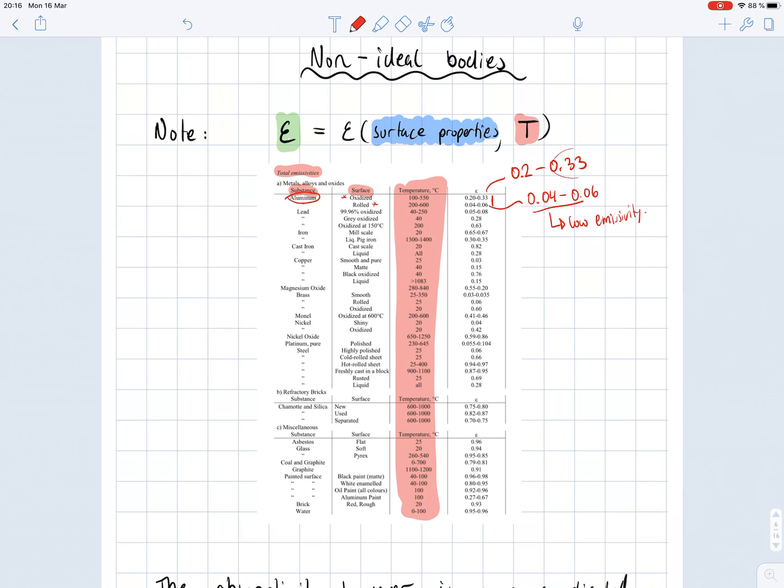And this one is a moderate emissivity. We see that the whole range of emissivities is used for the different materials that we are using in our industry. One important point is that these refractory materials typically have a quite high emissivity. Same is true for these, call them rocky materials, that have a high emissivity compared to the metals that we have here, that typically have lower emissivities.